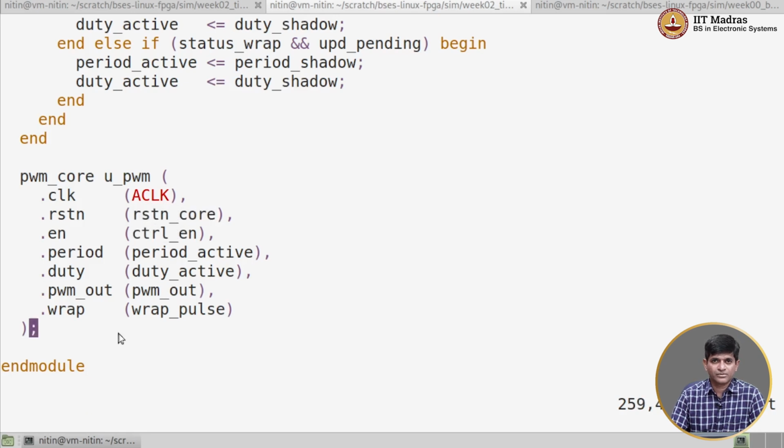software, right. So as you can see from here, we have taken a core which was designed without any background of hardware or of software, wrapped it in the AXI Lite structure which looks very similar to what we used for the register bank, added some functionality like write one to pulse, write one to clear and so on, and we have a module that can actually get integrated into any AXI compliant bus interface. Okay.